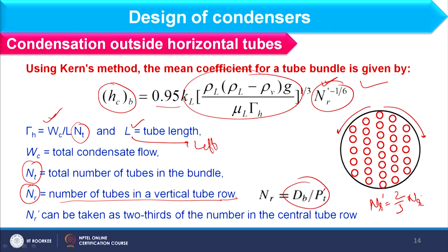So, in this way you should consider the corrected Nusselt correlation for computing the heat transfer coefficient in the tube, and the heat transfer coefficient in the shell side of horizontal tubes, right. And now I am focusing on condensation outside and inside vertical tube rows, okay.